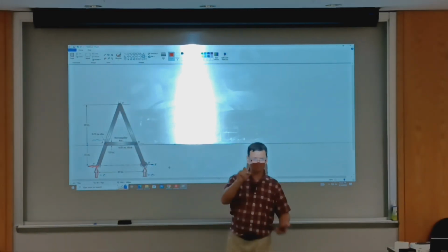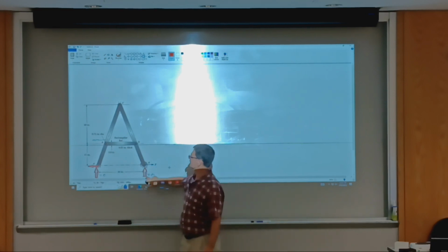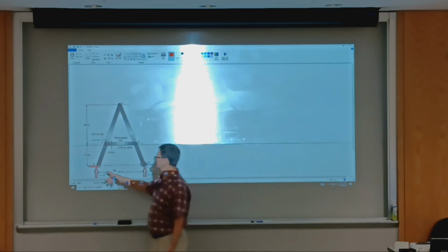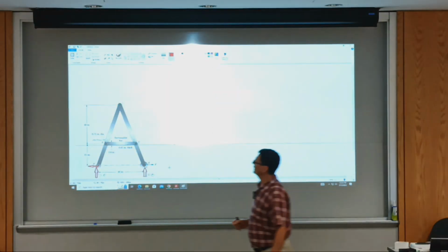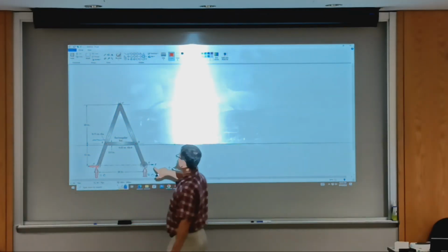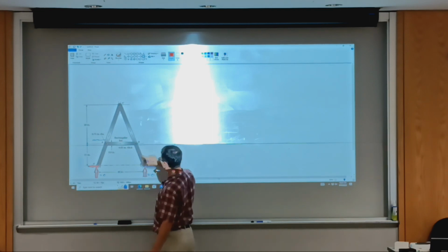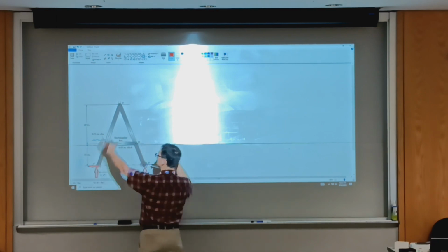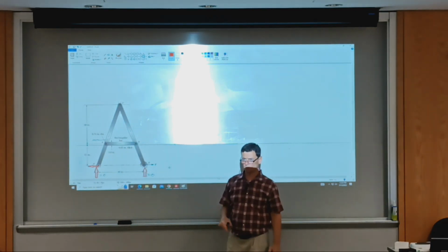You don't need to say sum of forces in the y direction equals 0, and just say this guy plus this guy equals 0. I don't know how to put it. So it's clearly because of symmetry, because of the particular type of loading, but otherwise you wouldn't include it. If, for example, I move this force above, like somewhere here, I'll start seeing forces acting here because of the tendency of the whole thing to pull this up and press the roller into the floor.